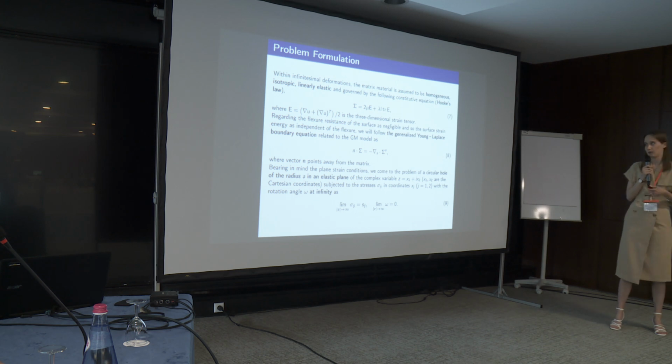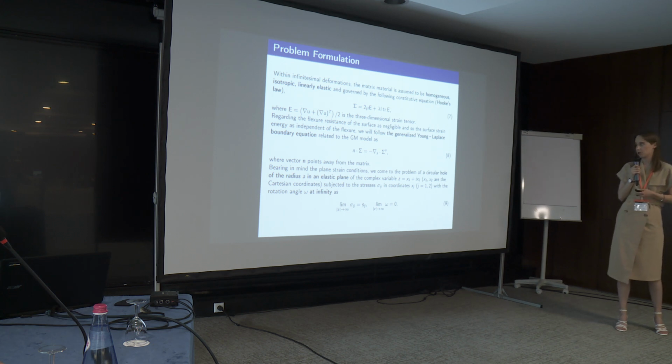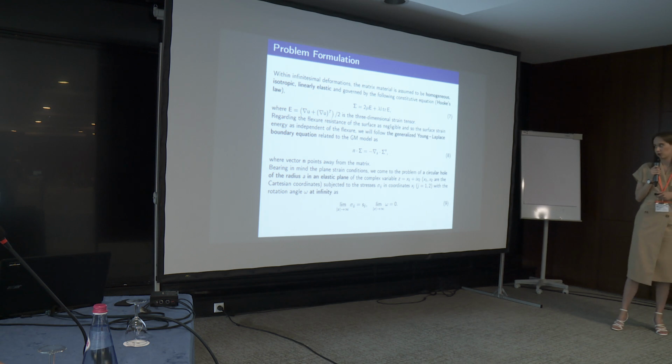So, if we make the problem formulation, we consider the matrix material, which is homogeneous, isotropic, linearly elastic, and the constitutive equation is formulated by Hooke's law. Also, we used the generalized Laplace-Young law in the form 8. So, we consider the problem in the case of plane strain for a circular hole of radius a in the elastic plane of complex variable. Thus, conditions at infinity are given by formulas 9.